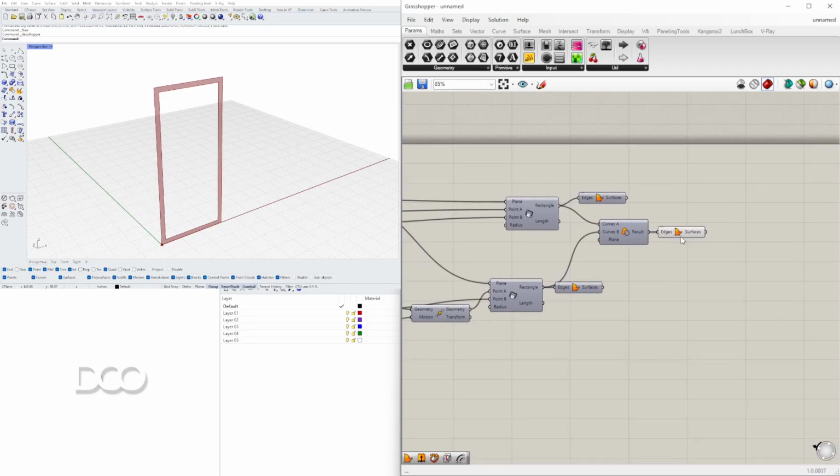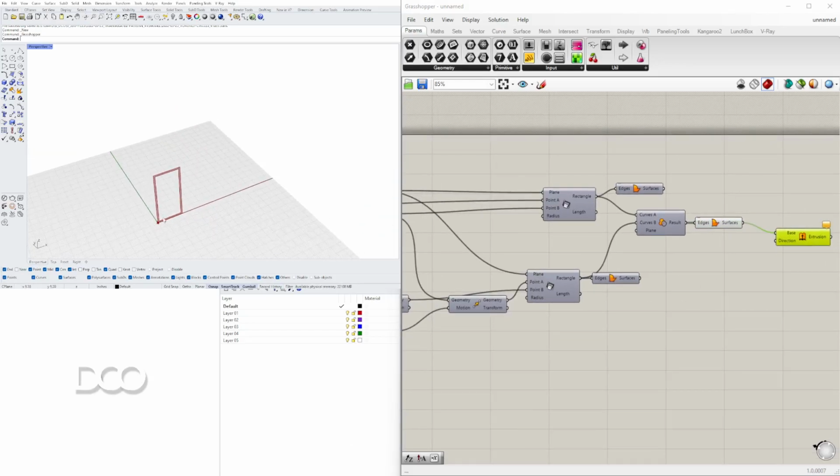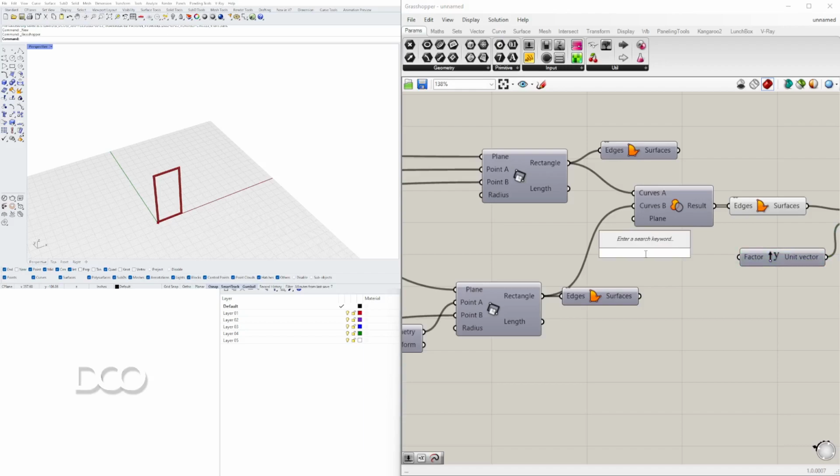Now what we're gonna do is take this and extrude. We're going to extrude this surface in the Y direction. The other thing is sometimes if you want to change the location, if you plug in an X or Y or Z value, if you're trying to change the orientation later, it might give you issues, but if you're just trying to create it standalone parametrically here, it shouldn't give you any issues. So we'll go here to extrude in the Y direction. And now we'll give the depth, so 24.